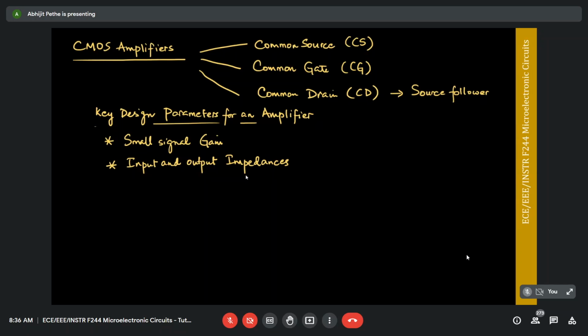All right. Anything else that comes to mind? Any other design parameters that you can think of? The range of saturation region. Good. What we call in amplifier parlance voltage swing. That is, we want to figure out that transistors remain in saturation. What is the largest swing you can get at any node? So voltage swing. Very good.